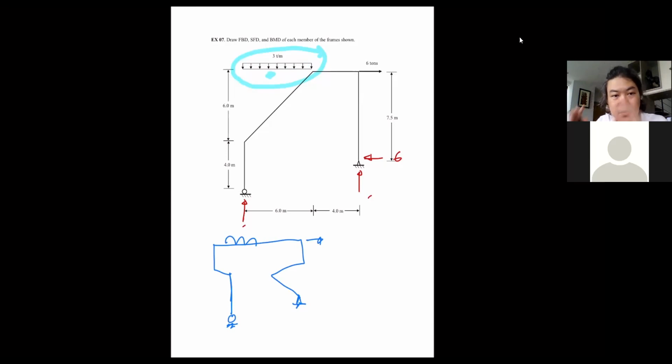So when you can see through this phenomenon of the reaction, the configuration of the frame should not matter, as long as it is elastic behavior. So you don't get confused by the shape of the frame. You just go on and calculate the reaction just like you do with statics. It's just one set of three unknowns. Okay, it doesn't matter what shape you have.